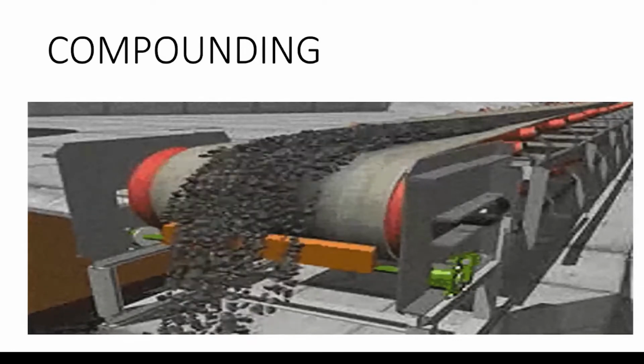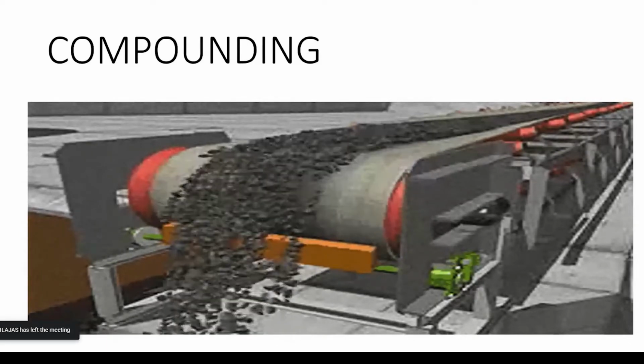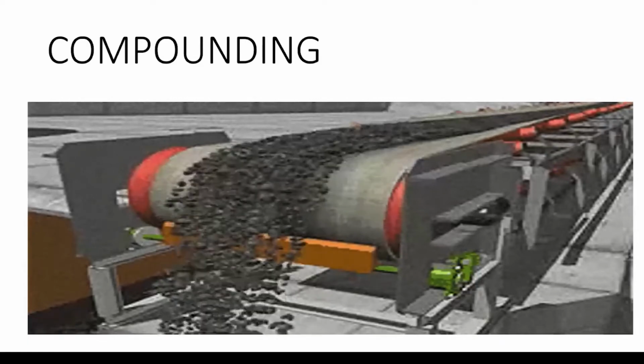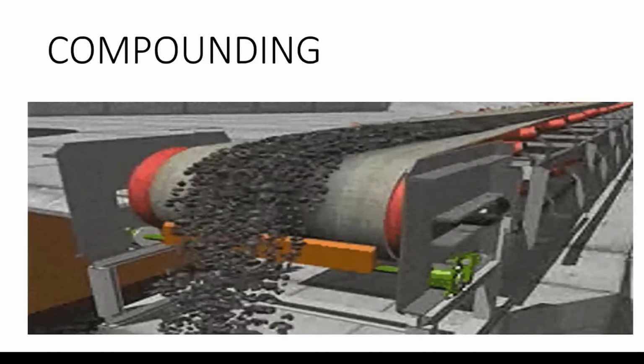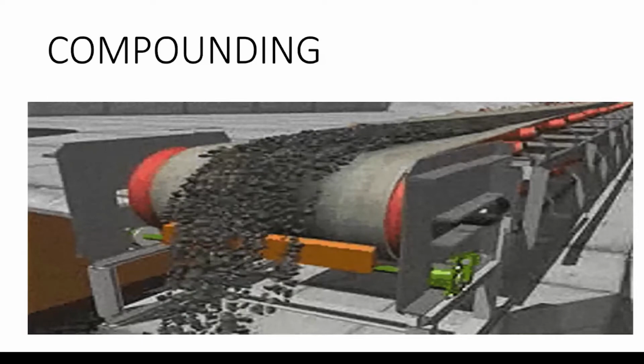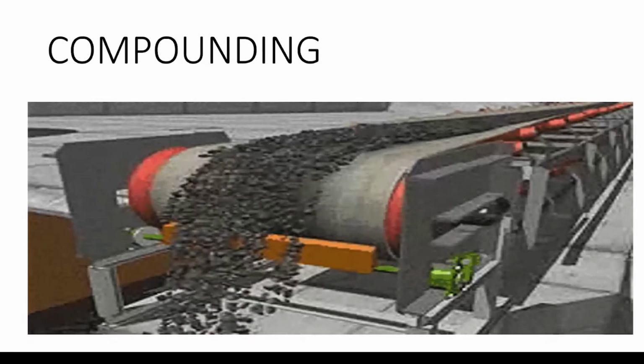Depending on the planned use of the rubber, other additives could include anhydrous aluminum silicates as reinforcing fillers, other polymers, recycled rubber, usually less than 10%, fatigue-reducing compounds, antioxidants, other chemicals and coloring pigments, plasticizers, softening oils, and mold release compounds.